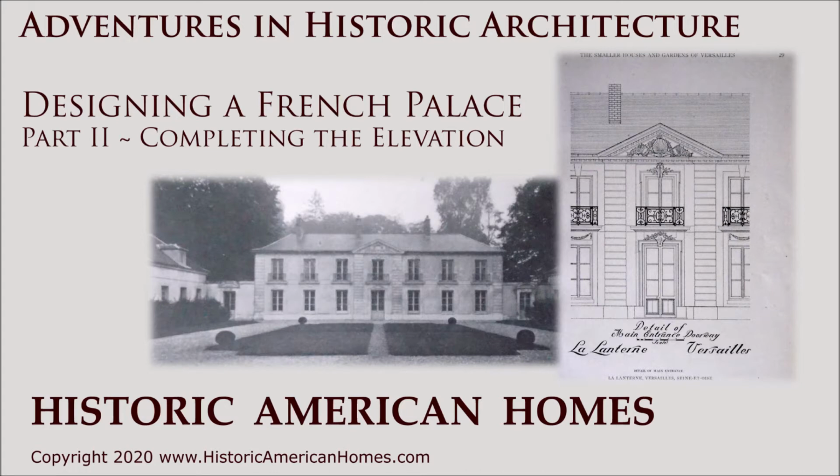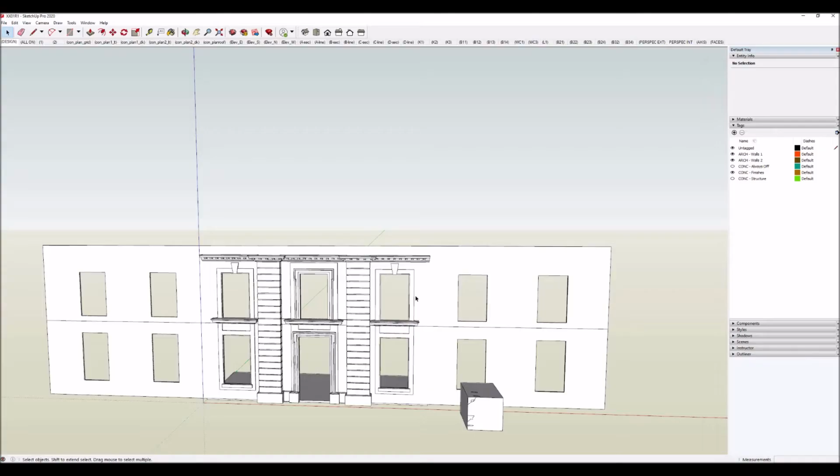In this episode, we're going to look at doing the pediment and the cornice, and working them out so that there's no distortion in the elements as we go into the angles. We've got brackets that need to fit into the angles. We're going to be using a few basic SketchUp commands to do all of this: just move, copy, and mirror, using components, mirrored components, to do symmetry.